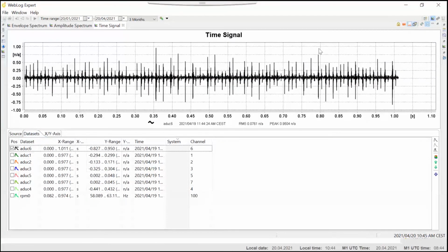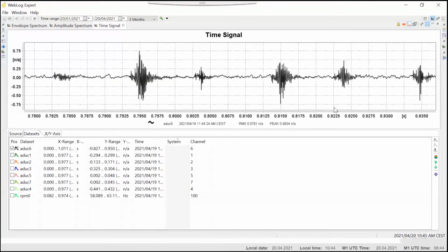in the signal. And if I zoom into these spikes, what we have is a number of repeat impacts. So what we've got is there's been this notch machined in the outer race. So every time a rolling element goes over the notch, you get one of these impacts. Now, it's easy enough to see in the time signal we've got an impact at a certain interval, and then you can relate the interval to how often a roller goes past a defect on the outer race.